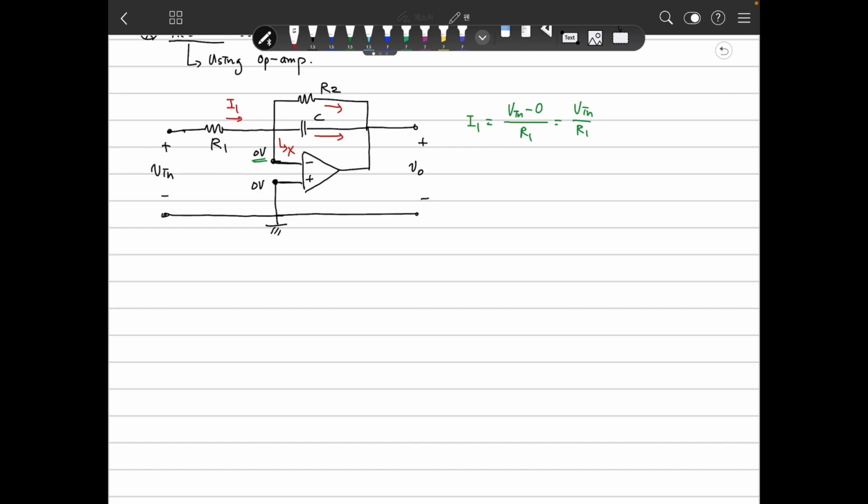So the potential Vout is 0 minus this impedance times I1. That is, R2 in parallel with −j/(ωC), times I1.